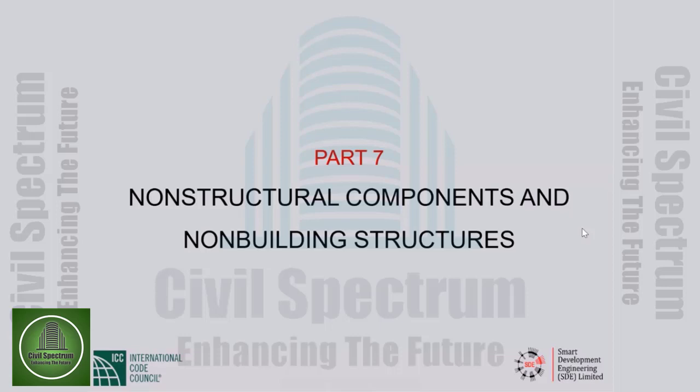In calculating the seismic deflections, remember interstory drift is deflection at level x minus deflection at level x minus 1. In calculating those, if you keep the gravity in place, that would be fine. The gravity that you should keep in place should be, I think BNBC tells you, dead plus 1/2 of the live load.